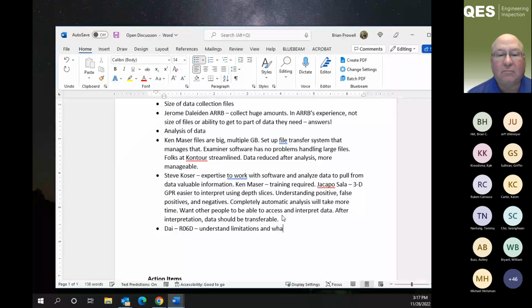Mike knows, they made stripped sections at NCAT that showed up very well on the 3D GPR, but not every stripping in the real world is just like that. Sometimes it is not very obvious, so how do we use GPR effectively to detect slightly stripped asphalt versus severely stripped asphalt?